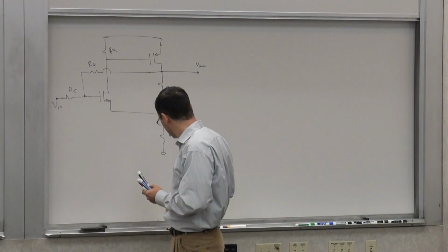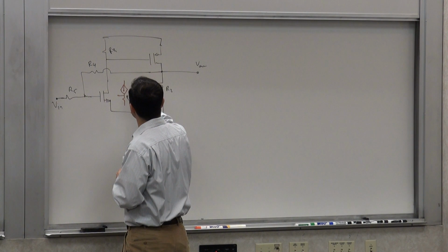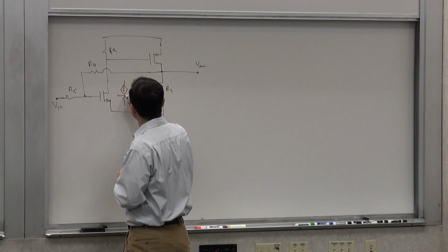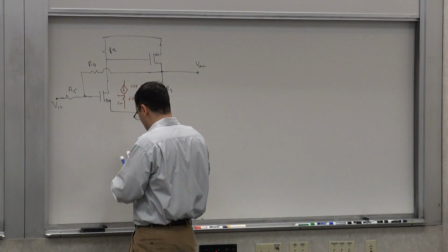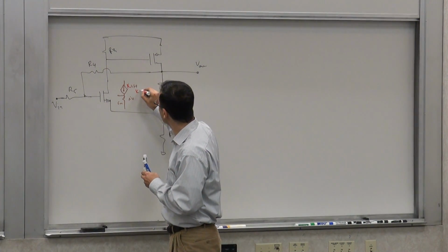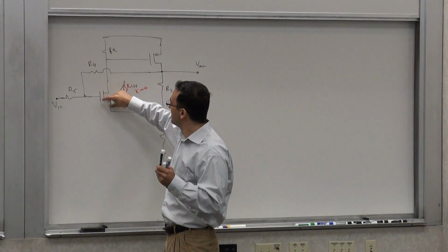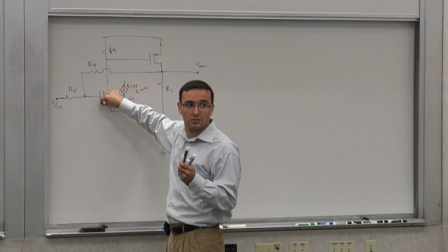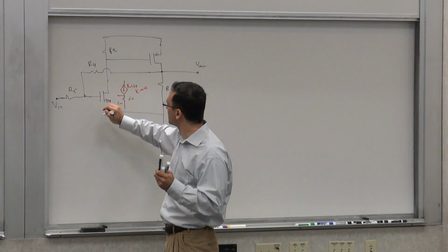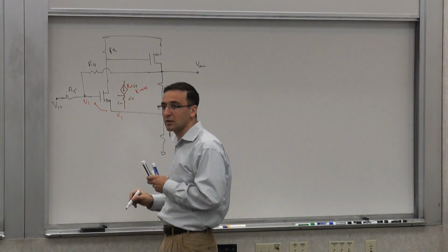Let's take the T model of this guy, and make this IS2, IS1 I guess, and this is IS1 and RM1 here. And let's make this the source of reference. So first calculating the asymptotic transfer function, K goes to infinity. K going to infinity here basically means that this needs to go to 0, asymptotically. So these two voltages are the same. Let's call this V1, same as V1, a small signal.